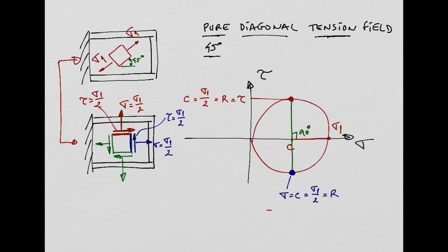That's why I like the Mohr circle. You don't like, but I love Mohr circle. Because I can get everything from geometry. All these stress transformations, principal stresses, maximum shear stresses, maximum direct stress, everything comes from just this circle, right? From geometry, from the center, from the radius, yeah?